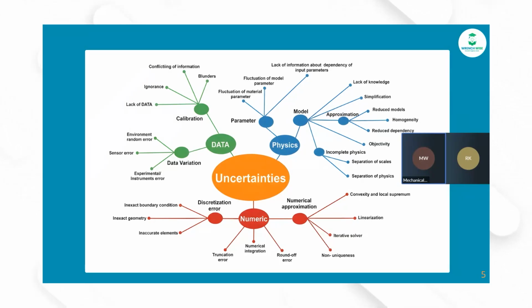Round-off error means that computers have a finite amount of precision, the floating point. Small errors can actually accumulate over millions of iterations. Similarly, truncation occurs when higher order terms in the Taylor series expansion are dropped to discretize your equation. Your first order versus second order, etc. Then ultimately the iterative solving itself: if the simulation doesn't converge, meaning that the residual between the current iteration and the previous iteration has not dropped beyond a particular threshold, then it is safe to say that your simulation is not numerically accurate.